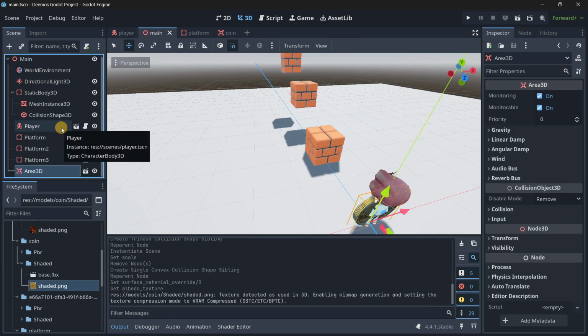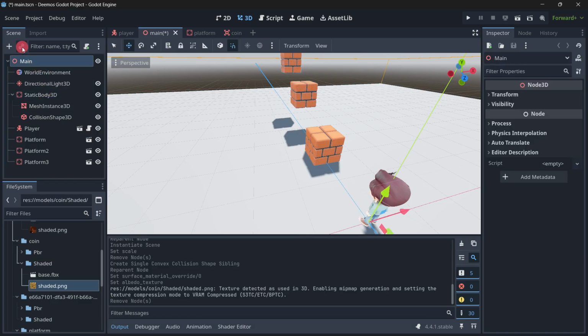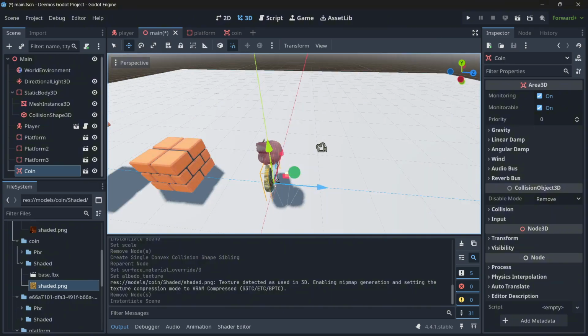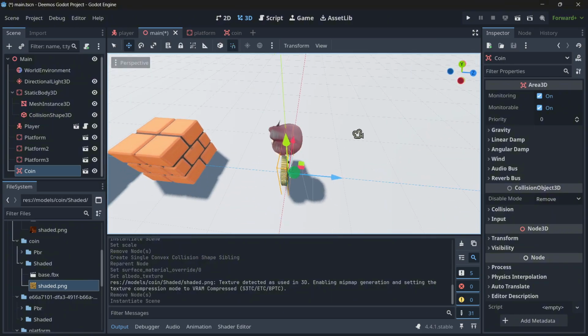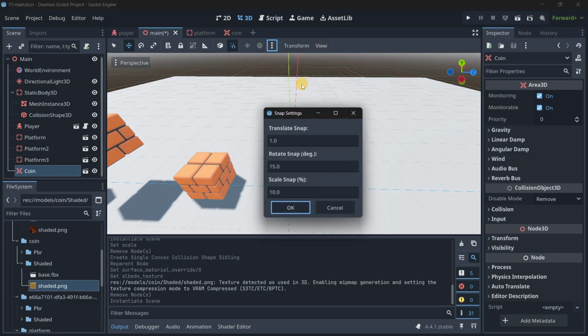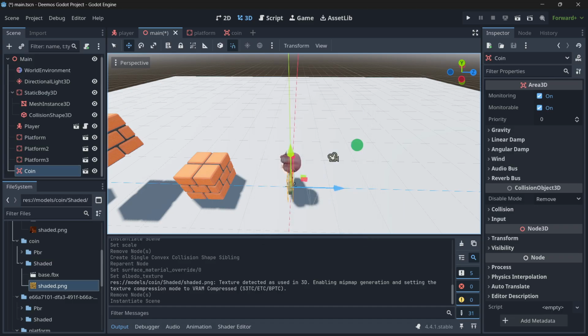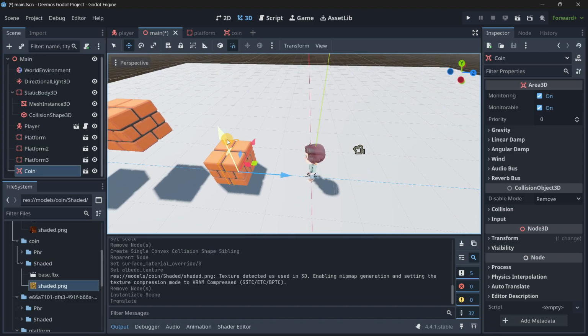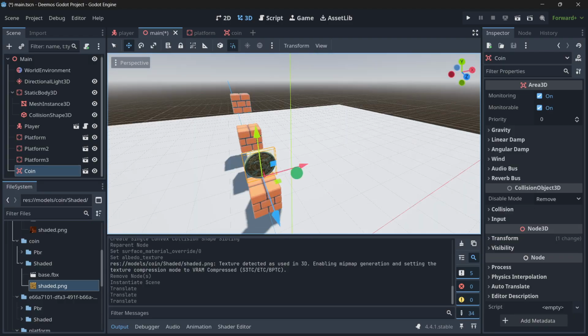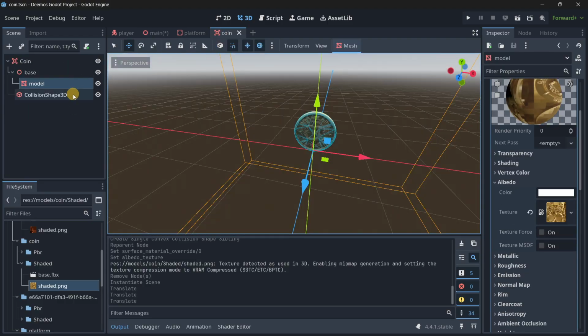This is named Area3D, but it was because the changes were not saved, so let's save it correctly. There we go. Once again, using the snapping, you can also modify the snapping. It was here, configure snap. You can modify the unit here, something maybe like this, and we should even make it smaller.